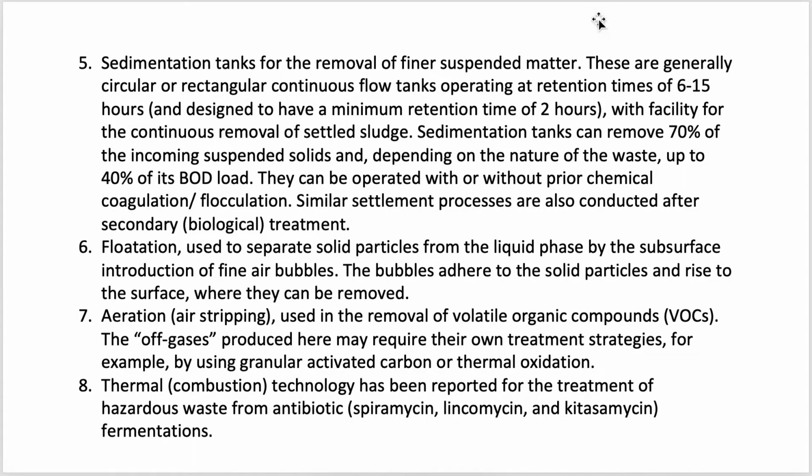Usually these are circular or rectangular continuous flow tanks operating at retention times of 6 to 15 hours, and this retention time should not be less than 2 hours. Also there should be a facility to continuously remove the sediment, that is the settled sludge.